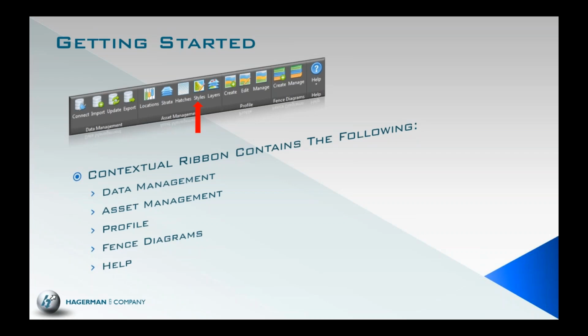Okay. In the Style Manager, we're going to be able to manipulate the different hatches that we've created. So we'll be able to add strata to these styles. We'll be able to give them a color. It's going to be very similar to, again, our Map 3D setup. Okay, so when we bring in our FDO objects in Map 3D, we can actually give them a color, etc., and transparency, so on and so on. Okay, we've got our Layer Manager.